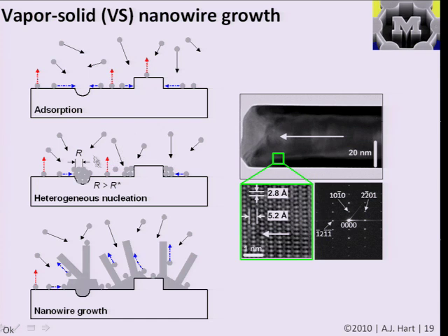And over time, the atoms start collecting in certain areas of the substrate. And in fact, substrates aren't often perfectly smooth, there are places that are little bits of roughness or little cavities. And because the energy change is greater if the atoms stick in a corner like so or stick in a little divot like so, you'll find that at locations that are rough, you end up forming clusters and the atoms collect. They might stick for a longer time, and therefore if you have a condition where you surpass this critical threshold for nucleation, you end up forming clusters on the surface.